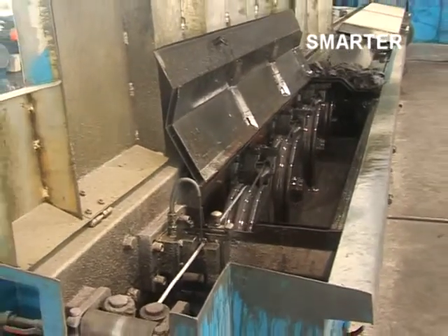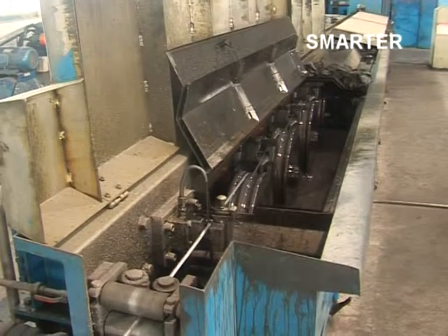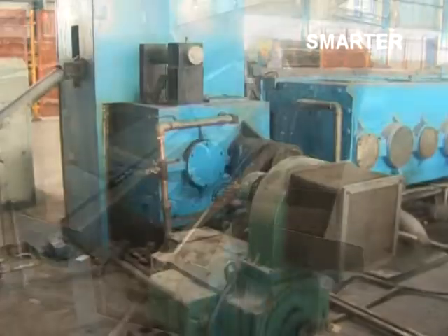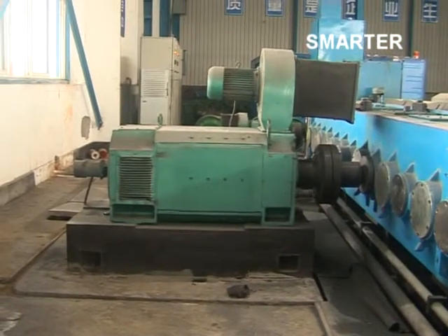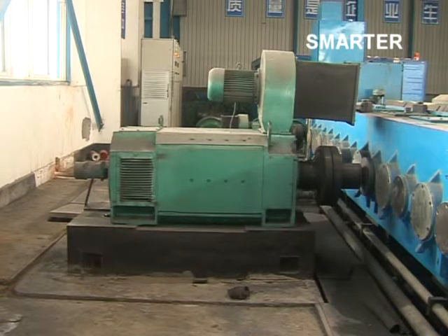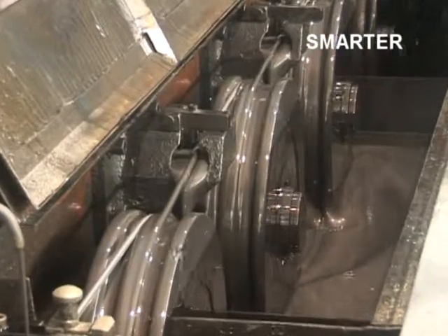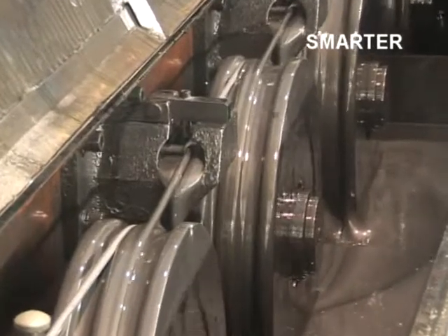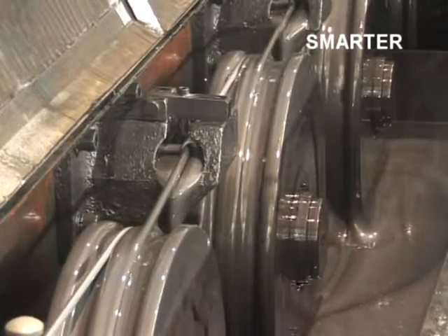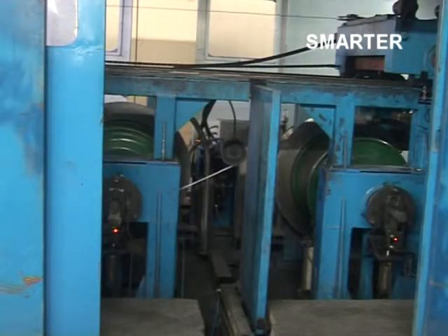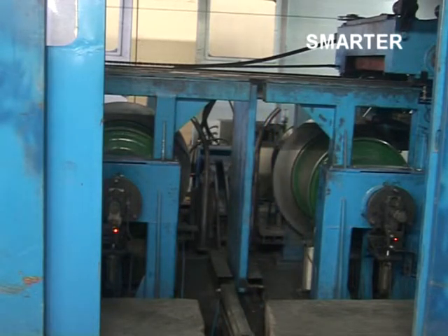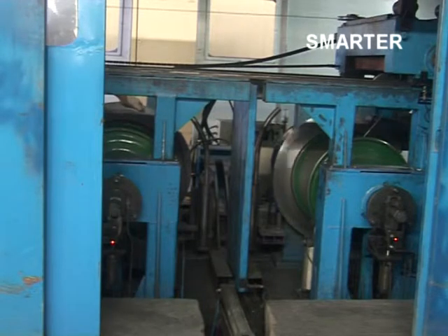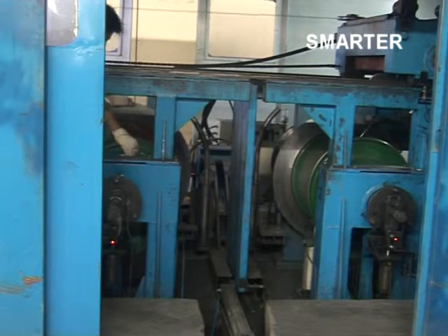The emulsion tank and the gearbox are separated to avoid mixing of the 2 liquids. Final capstan and other capstans are driven by separate motors, whose speed could be set and adjusted, with fast dies interchanging. The die of diameter regulation is rotary, which could ensure the roundness of the wire as well as improving the service life. Dual spooler for taking up when the length reaches the setting, automatic bobbin interchanging, pneumatic lifting, clamping, and releasing the reel pneumatically. This kind of take-up also has a wire pressing unit to keep the wire from loosening.